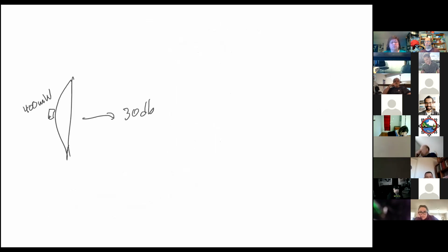with dish antennas here in our club with a transmitter that is 400 milliwatts. We use it for long distance Wi-Fi over ham radio. We have a forward gain of 30 decibels because it's a pretty big dish antenna. So the question is, what is our effective power going forward? Okay, what is 30 dB? How would you break that up?